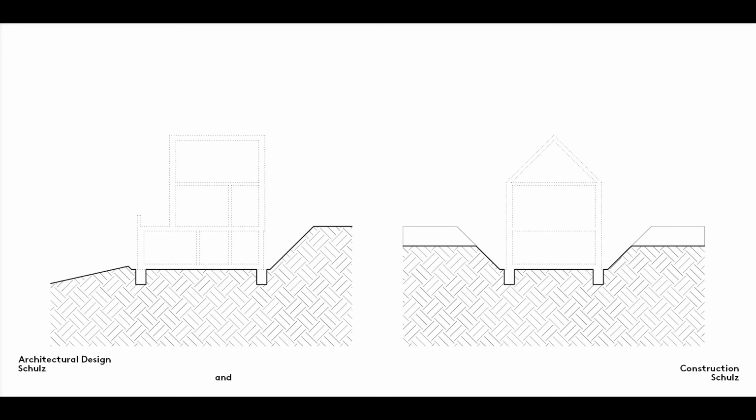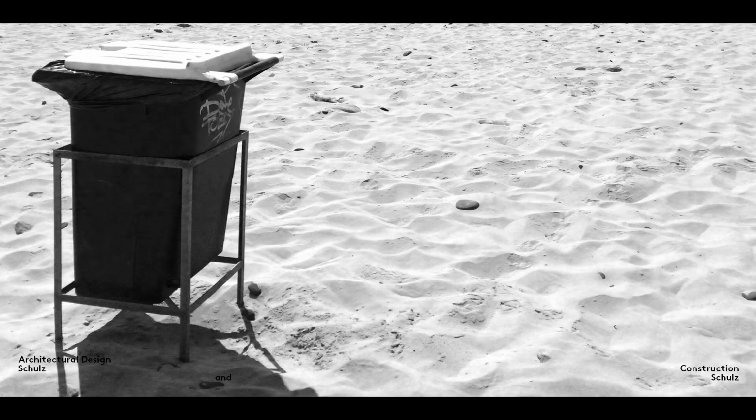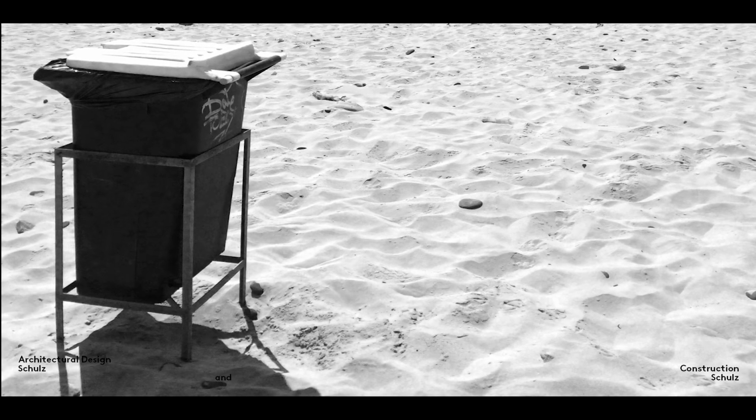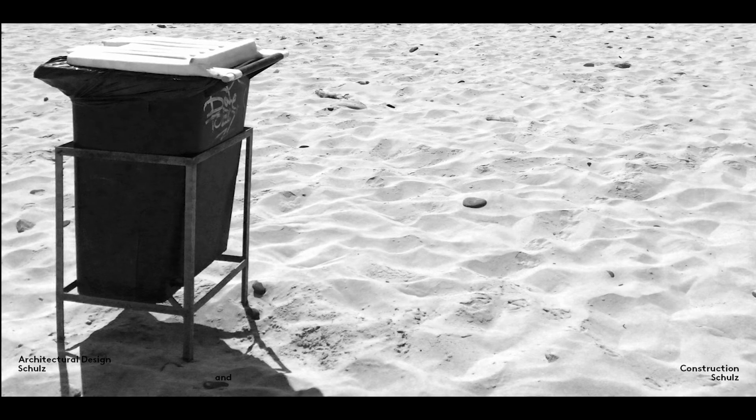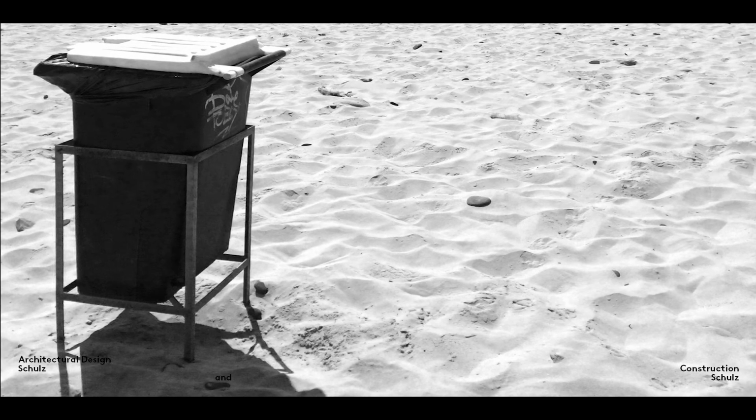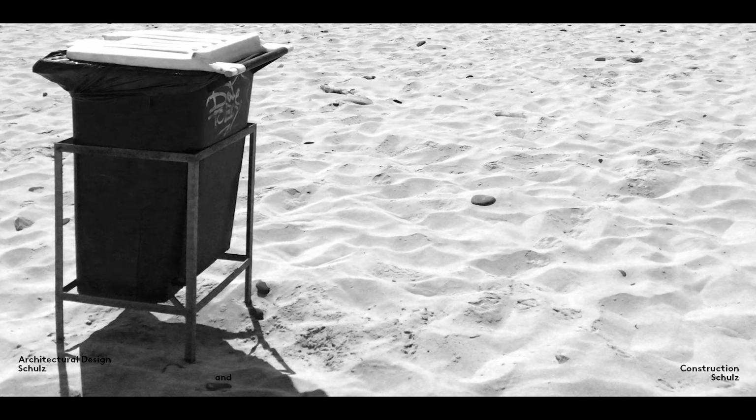Buildings are erected on an underlying supporting structure that is in turn placed on the ground. The contact surface between the foundation elements of a building and the ground is a critical interface. The foundations may take the form of pad elements to support single-point loads, such as structural columns, for example. Linear elements, as in the case with strip foundations under walls, or flat elements, as in a raft foundation. The type of foundation depends primarily on the concentration and distribution of the loads, single point, linear, or full surface, and the load-bearing capacity of the ground.